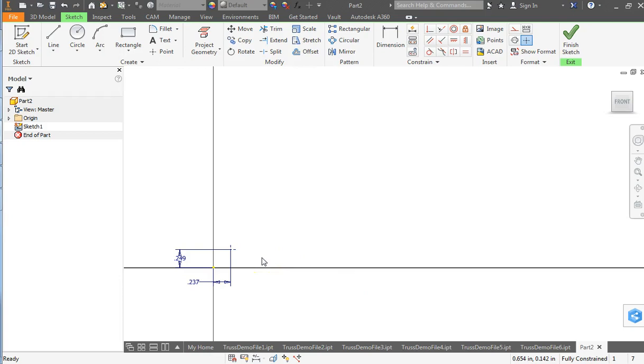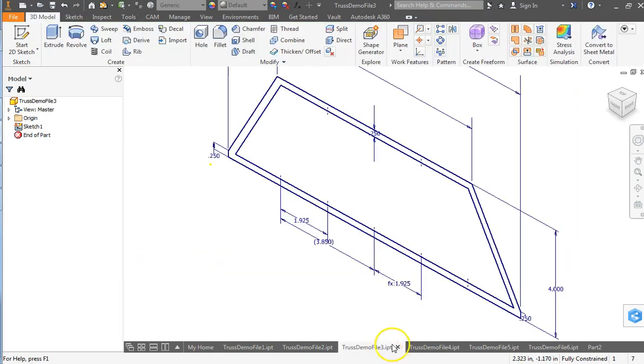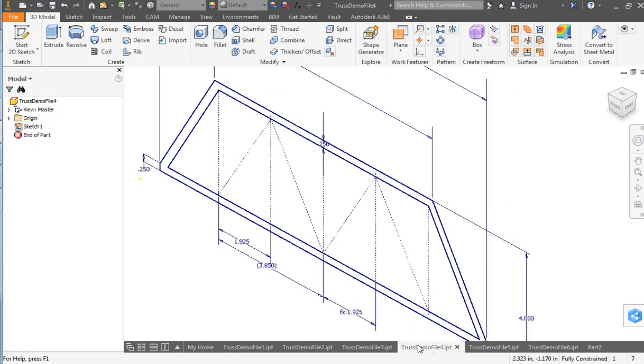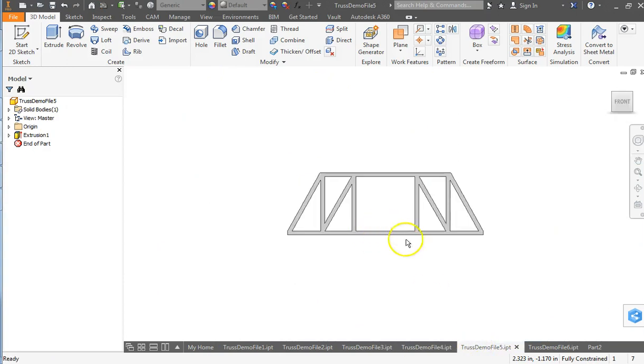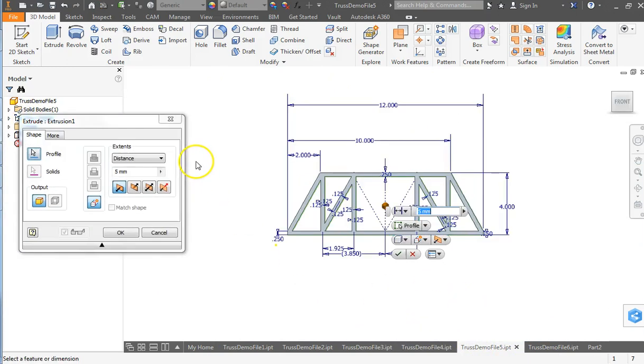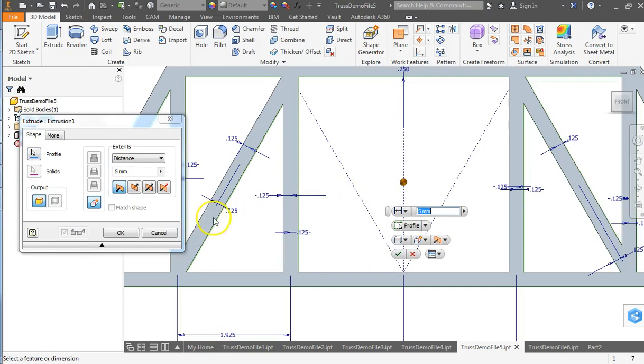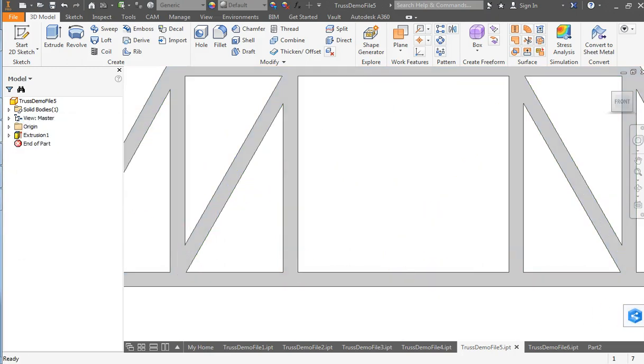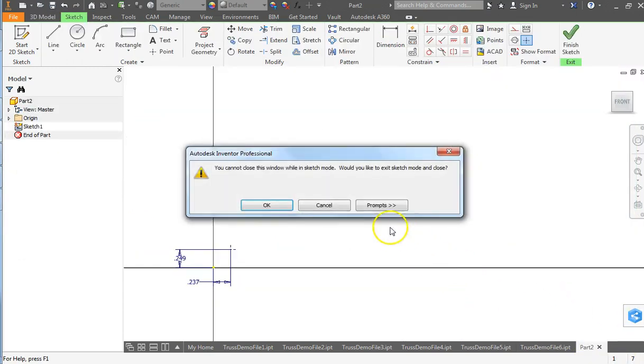The reason why we want our sketch to be fully constrained is as we walk through this process of building the bridge, especially when you start applying dimensions, like trying to get these outer edges to be dimensioned into place. If the earlier geometry has not been fully dimensioned and locked in place, it might move on you instead of the new things that you're trying to get to move into position. Okay, so that's why it's really critical that we are dimensioning as we go.